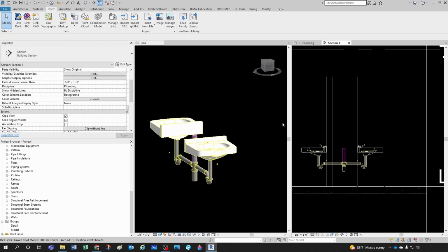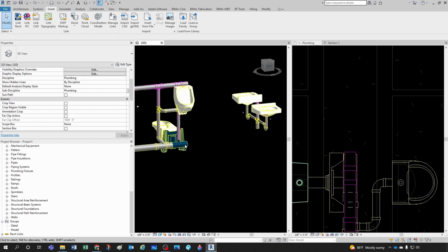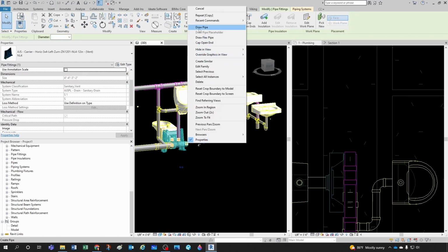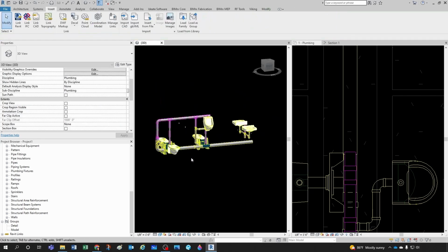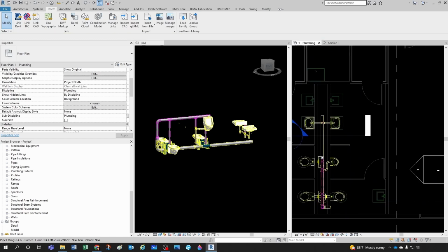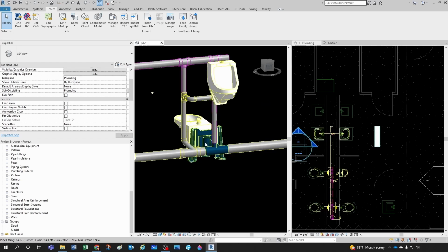and this is looking pretty good sanitary drain wise. So let's see, what are we missing? So out of this carrier, we have to keep going, right? And if you hold your shift key, you go orthogonal, so that's pretty useful. Okay, again, I'm not sloping this pipe. I should be sloping this pipe, but the only reason why I'm not sloping it is because this chase is mine. It's completely mine, and these carriers have adjustable plates so they can play with those inches,